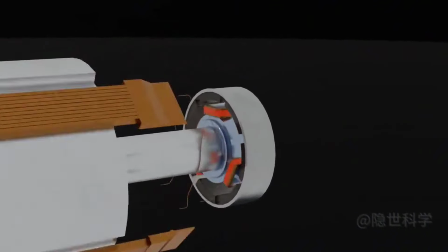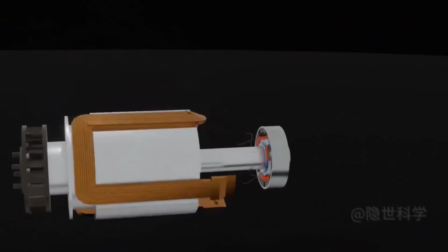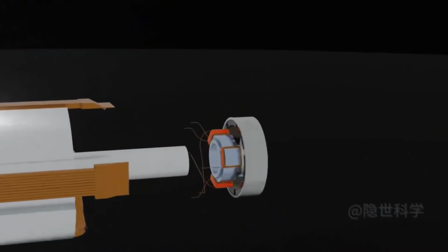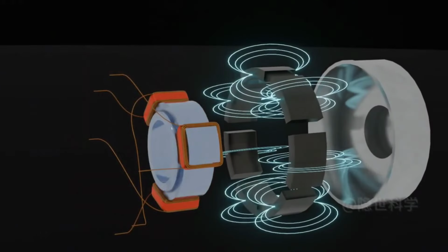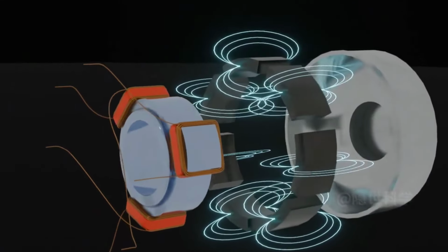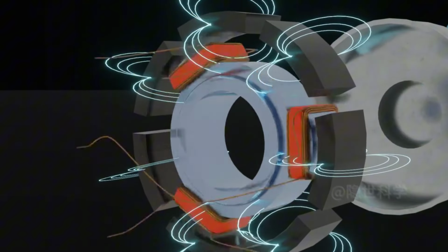The working principle is almost the same as a general generator. There are two components, the rotor and the stator. The stator provides the magnetic field. In this case, permanent magnets are used, and the rotor is the coil that the magnetic field cuts. The rotor of the PMG has three coils, so there are three outputs.